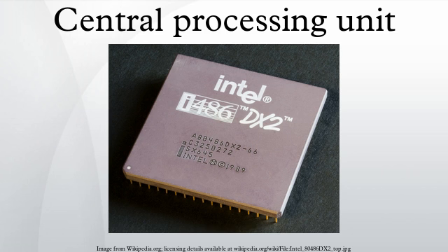Two notable examples of this are the ARM-compliant Amulet and the MIPS R3000-compatible MiniMIPS. Rather than totally removing the clock signal, some CPU designs allow certain portions of the device to be asynchronous, such as using asynchronous ALUs in conjunction with superscalar pipelining to achieve some arithmetic performance gains. While it is not altogether clear whether totally asynchronous designs can perform at a comparable or better level than their synchronous counterparts, it is evident that they do at least excel in simpler math operations.